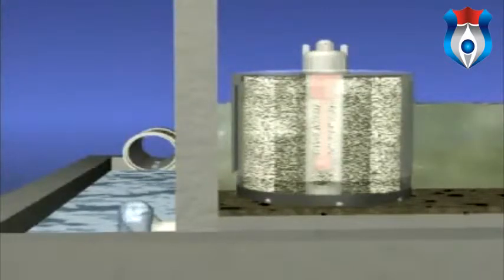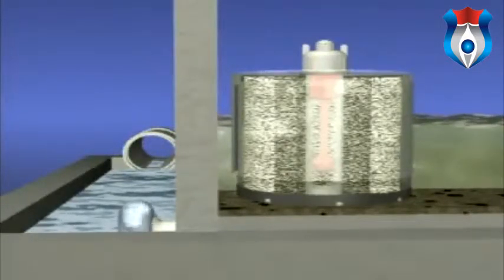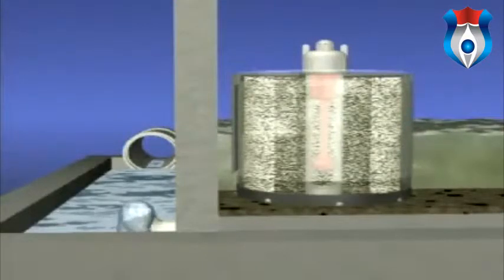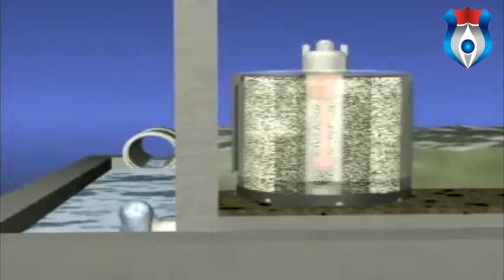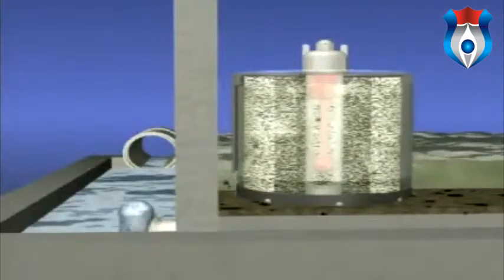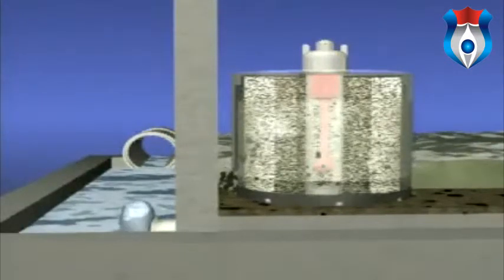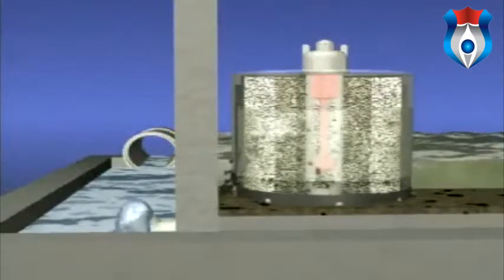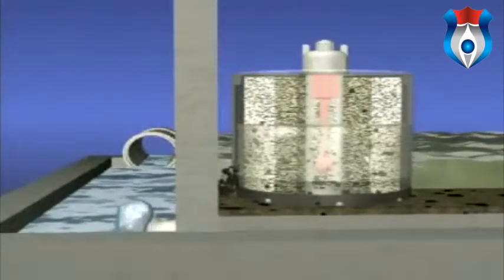The siphon increases the flow potential and distribution of pollutants across the filter media, increasing the effectiveness and useful life of the filter cartridge. The siphon effect continues until the stormwater in the vault begins to subside. A hanging water column will remain under the filter cartridge hood until the water level in the vault reaches a series of scrubbing regulators on the bottom of the hood.